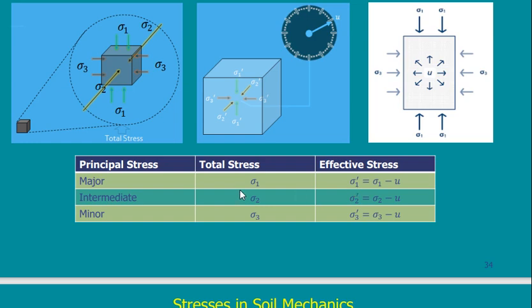If I ask you what is the effective stress, we just discussed this at the beginning. If I have stress carried by the water, then the effective stress is the total stress, and I have to deduct from it the part that was carried by water.